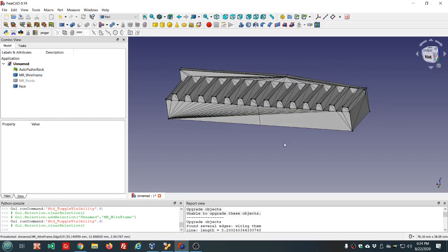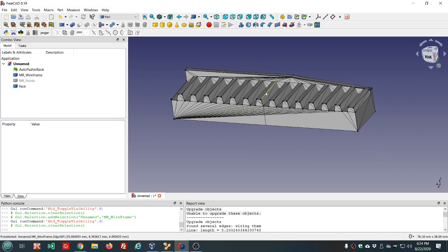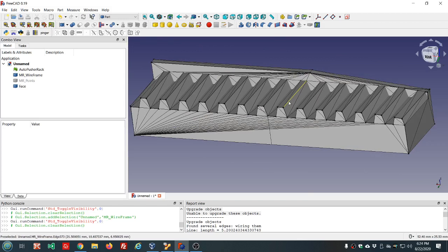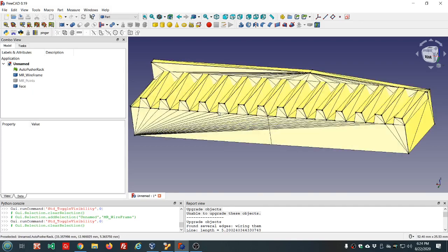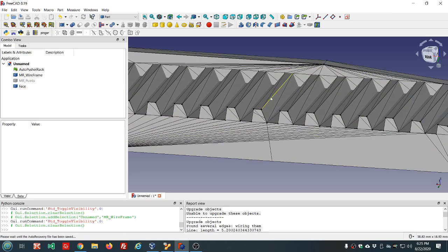So we can extrude this face back to reach this wall here. But how far do we need to go? Another option is we could sweep along one of these edges, but I recommend extrude instead of sweep because it's going to be more parametric. If you decide later on you wanted this to be longer in this direction here, then you could just change that extrude value, or you could extrude in both directions. You'd modify the length property of the extrude object.